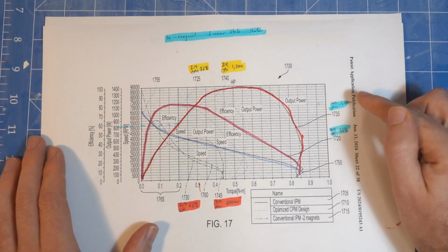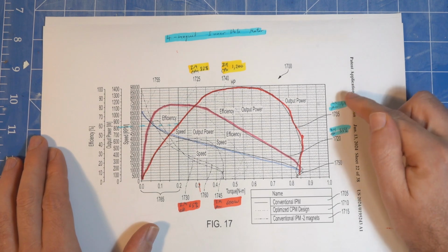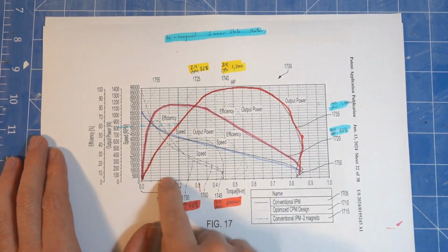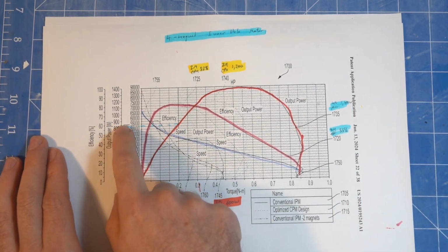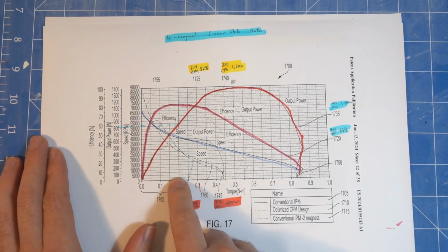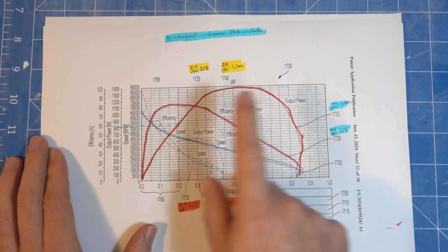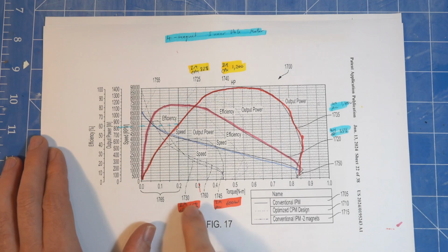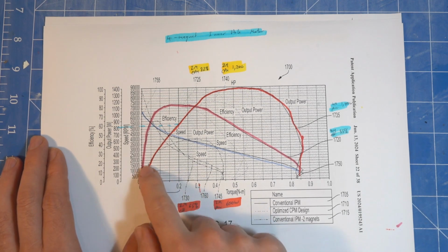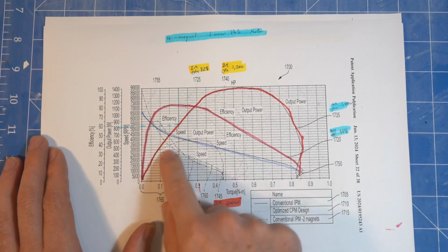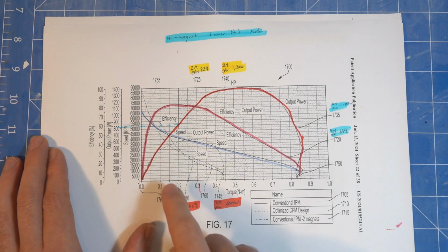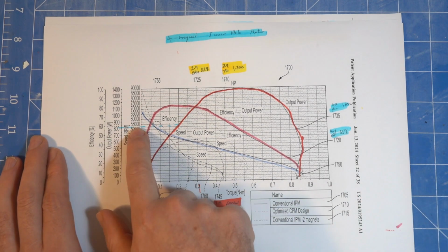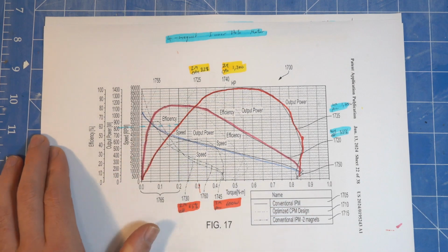So this one, they call it a 1,400 watt motor, but in the operating region it's more like 800 watts. And peak efficiency of 85%. And the Consequent pole motor's, I think, 82%. And then the 5 pole motor's garbage. That's its power curve. It peaks at 600 watts and peaks at 65% efficiency. Pretty high RPM, 50,000 RPM.